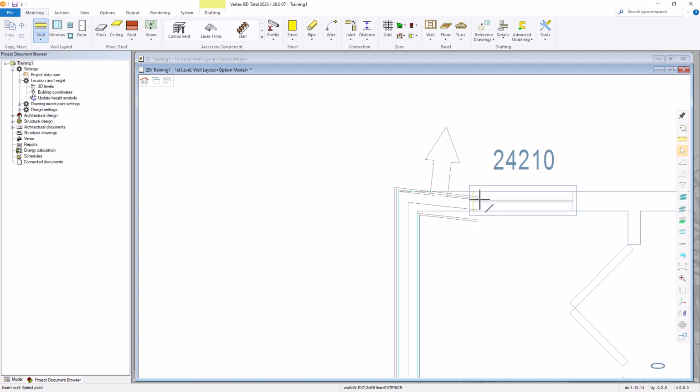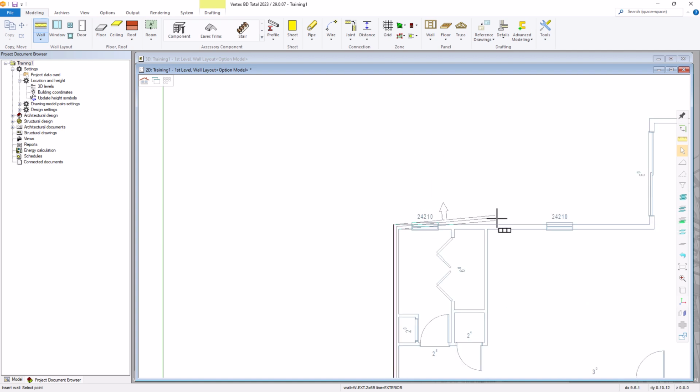So I'm going to hit I. Now I'm going to go over. I could just go in and get that yellow dot and hit the horizontal, and I'm pretty confident that that's a true horizontal line. But you can always use the U key to confirm it is horizontal and locked in the X-axis. And click OK.